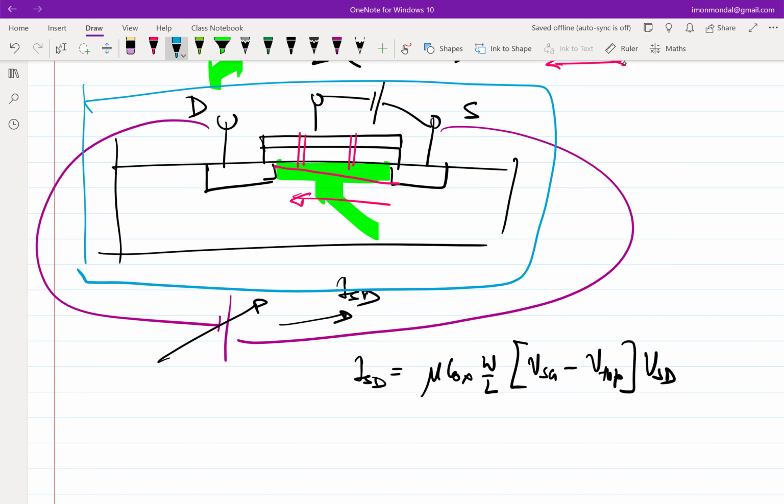It's a resistor, right? Now, if I know that another terminal comes out of this box, which controls this VSG, then I can control the value of the resistance by changing VSG, right? So this essentially becomes a voltage variable resistor. You don't have to pluck out a resistor as you do on a breadboard, for example. You targeted 1 kilo ohm, maybe it's 2 kilo ohm, so you have to pluck it out and then put another 1 kilo ohm back.